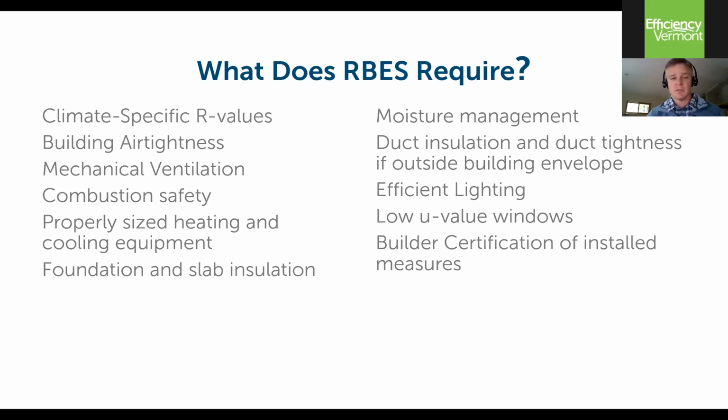Mechanical ventilation: we do need to provide adequate and well-maintained indoor air quality to manage pollutants and moisture, relative humidity within a building. So active mechanical ventilation is a requirement. Combustion safety: making sure that what we're using in our buildings to heat and cool them are not creating unsafe and unhealthy conditions because of not drafting appropriately and not being tuned appropriately.